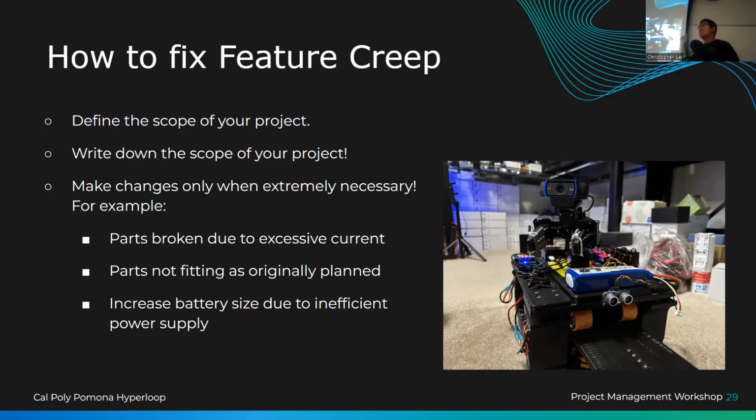The original plan for this pod was to be powered by a 2S LiPo battery. Now that you all know what LiPo batteries are, I can say that. So a 2S LiPo battery is not enough to power the motors on the car, so I upgraded to a 3S LiPo battery. This is technically feature creep, but it is necessary to solve this problem, so that's why I did that.